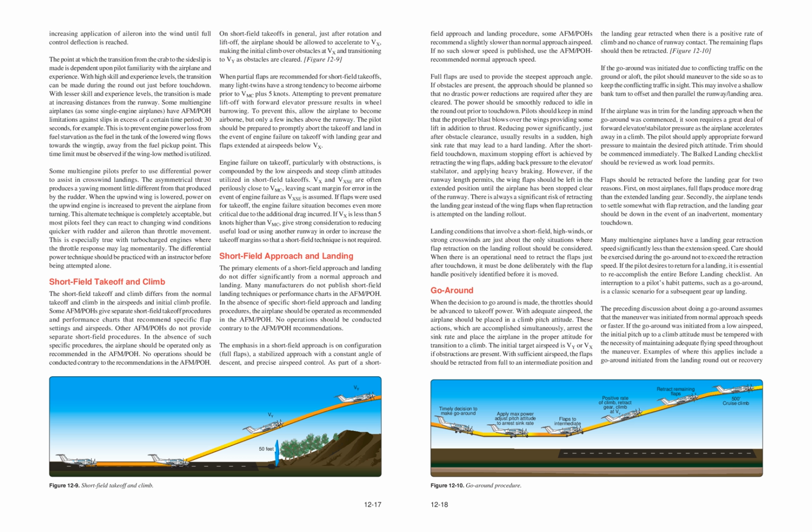The emphasis in a short field approach is on configuration, full flaps, a stabilized approach with a constant angle of descent, and precise airspeed control. Figure 12.9. Short field takeoff and climb. Short field approach and landing procedure.